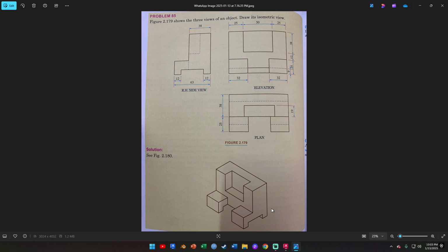This is how we're going to construct the shape now inside the box. So we're going to start by constructing each view one by one, the front view, the end view, and then the plan view. So we're going to start with the front view first. Alright, an isometric projection is very simple once you start with one view, and once you take every measurement or every dimension piece by piece.